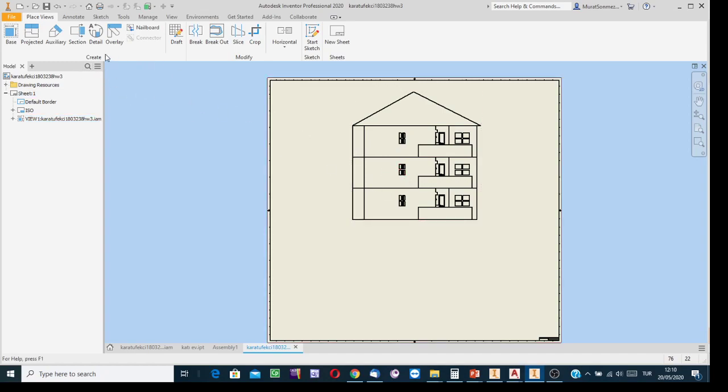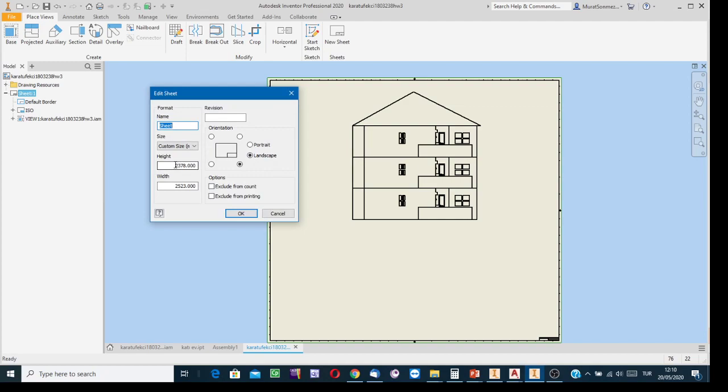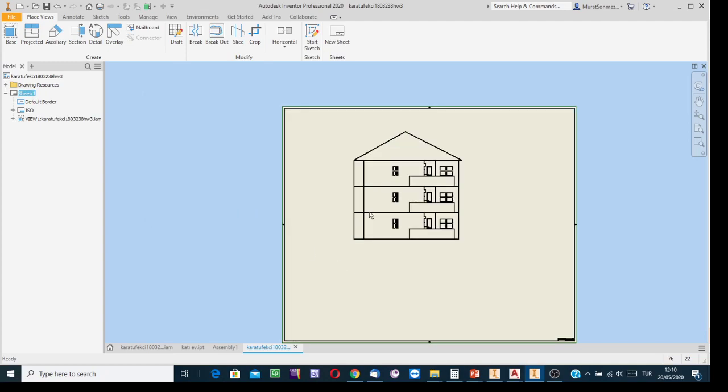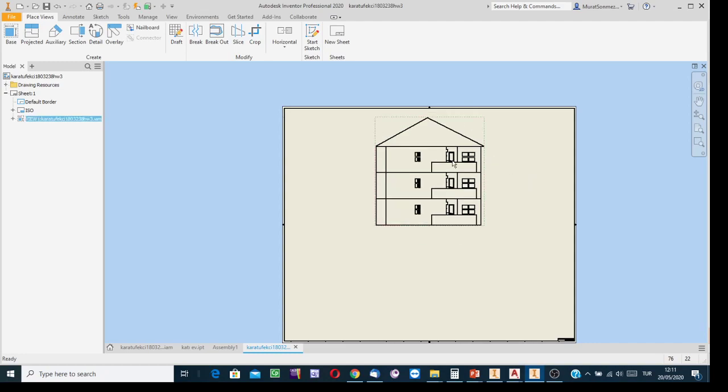How about the plan view? It is a sectional view, you know. Create the sectional view. But here, for the sectional view, the empty space may not be sufficient. So I'm going to increase the height, saying that 3000 millimeters is the height of the paper. And then start the sectioning process, clicking on, you know, this, indicate the view, and then